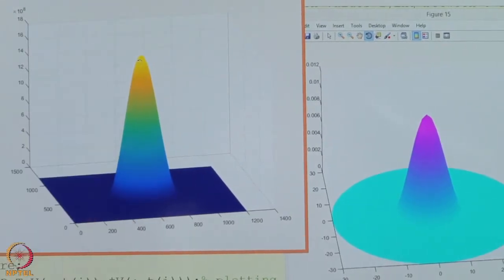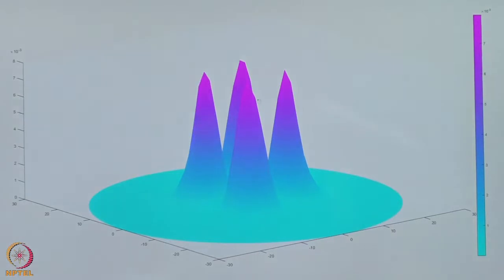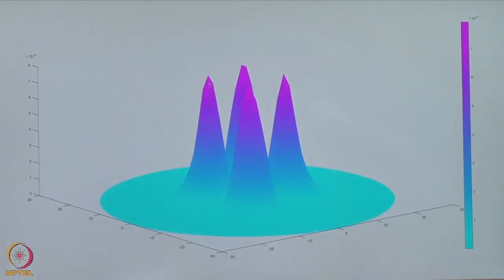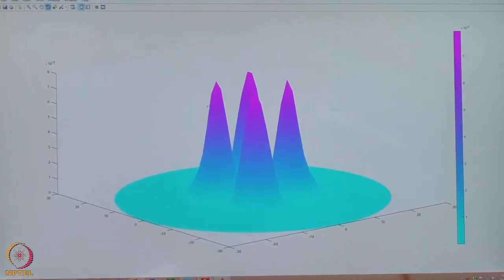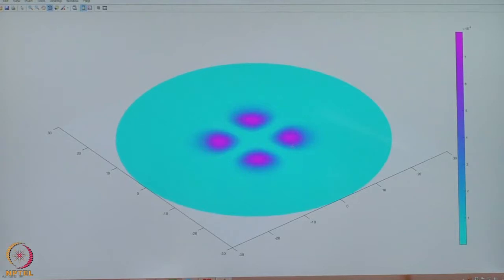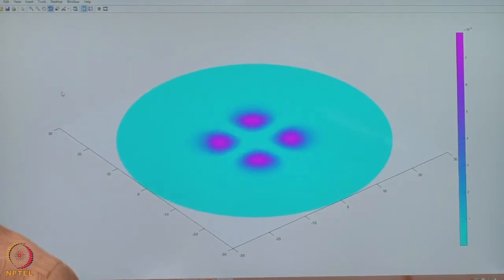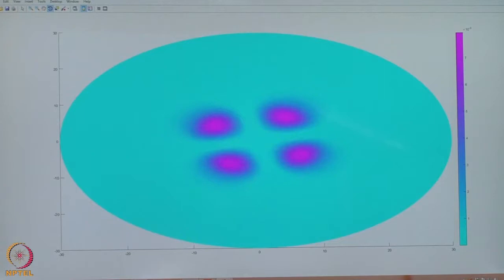Can you also show us the higher order modes that we have got? And here again the meshing has improved the angular part. So maybe you can see also in the XY plane. Again, if you see the XY plane, the triangular portion that we were noticing before has been improved, and we get a kind of smoothness in the surface. Okay, so this is the direct result of the finer meshing. So the error is converged. If we go further finer, then this will be further improved. But again, our computation cost will be quite large.